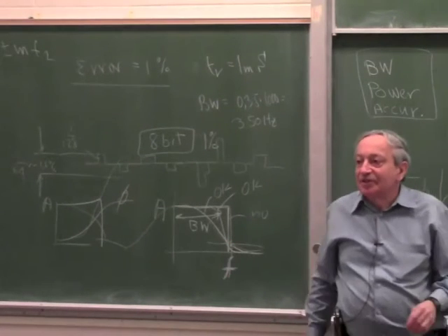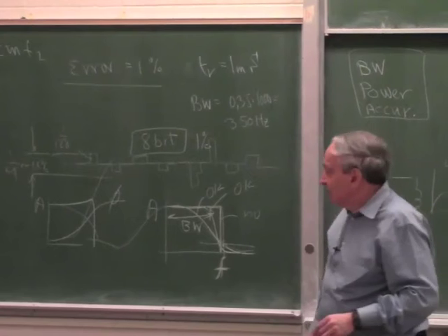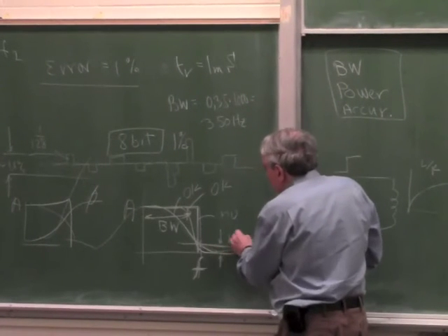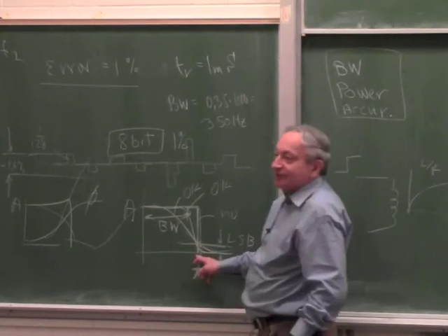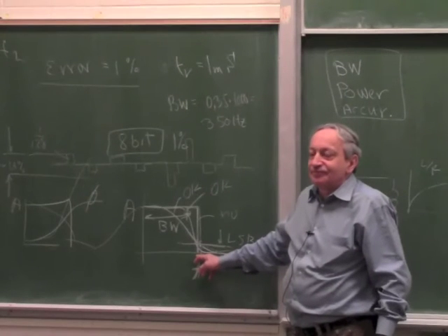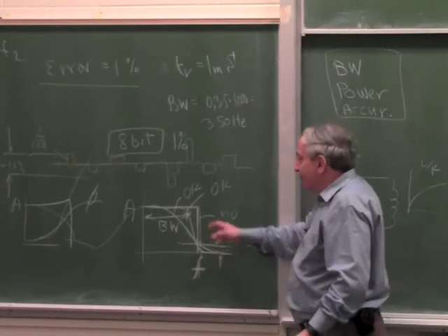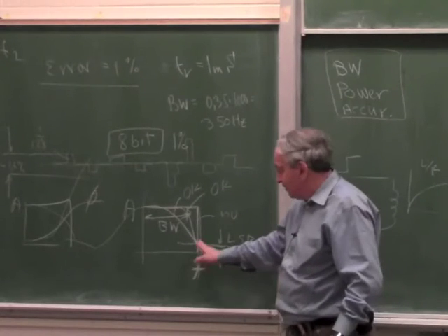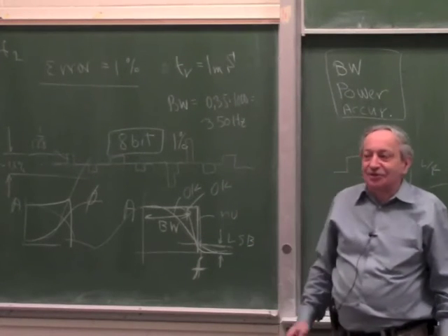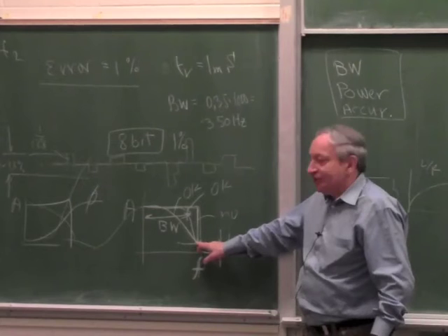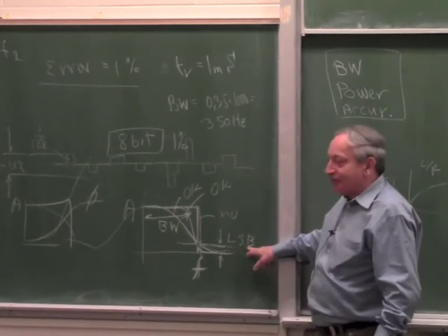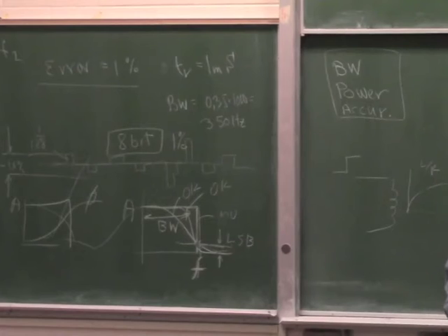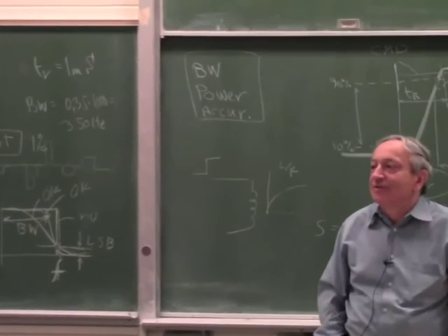The accuracy of the least significant bit. So this has to be less than the least significant bit, but at what frequency? Because every filter eventually will go down to a least significant bit, but the question is where? So the two coordinates of this important point, it has to be less than a least significant bit at what frequency?